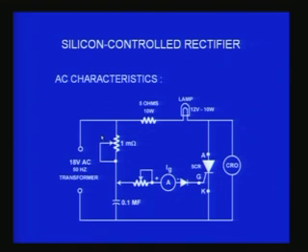For example, what I have shown is a very simple thing, of which I will also show a demo. I have applied a voltage source here, and I have an RC combination here, resistance and capacitance, and the RC combination can give you a phase shift, and that phase shifted sine wave is what I am applying, after rectifying through the diode, as a gate current. So I can convert the AC into a rectified DC that is coming through the gate, and change the position by changing the phase shift using this RC combination, and thereby I will be able to control more than 90 degrees on the gate pulse.